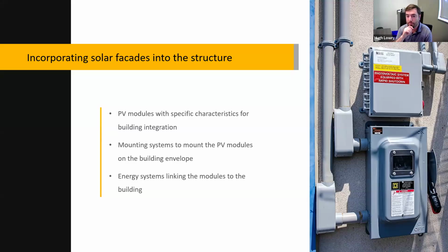You can see an example of a photovoltaic rapid shutdown initiator in the background of the system too. So you see that little red thing just to the right of that box. That is the button that firefighters would hit in order to activate the rapid shutdown on this system. Below that, you can see another example of a disconnect switch. In this case, the disconnect switch has a window. It's because it's an exterior disconnect switch, and it's one that the firefighters could technically throw. We want to make sure that you're able to see into the exterior disconnect to make sure those contactors are disconnected. So that's why that one has a window.